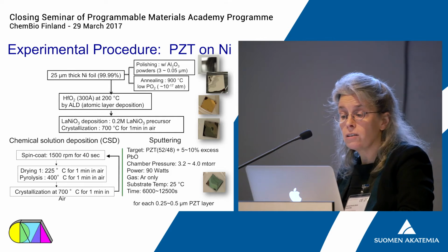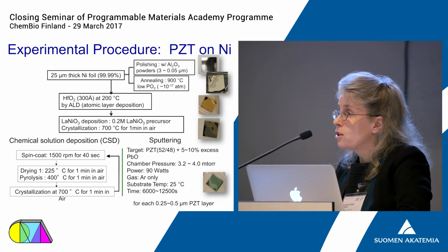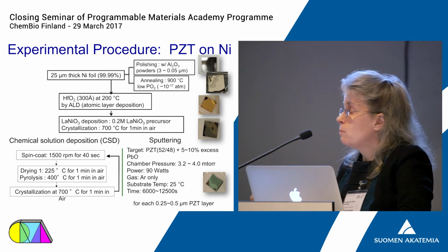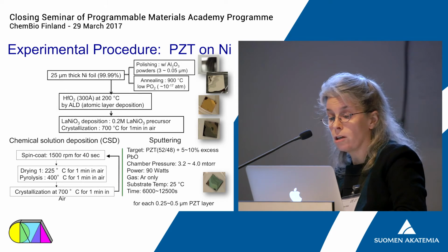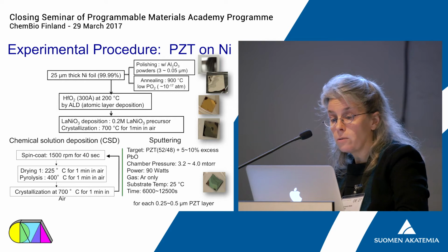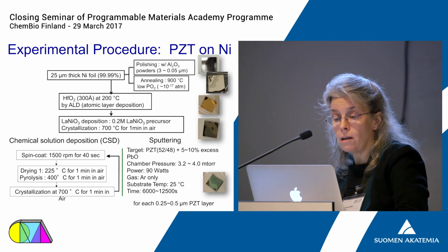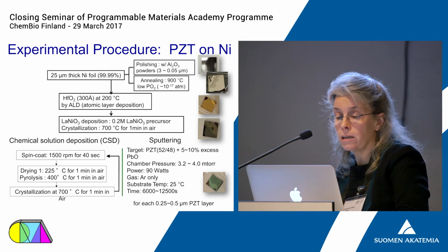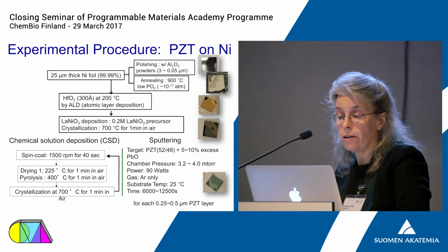They will deform plastically as needed, and they also have larger thermal expansion coefficients than lead zirconate titanate, so they offer the opportunity to be able to make machinable microelectromechanical systems as energy harvesters with good figure of merit, to be able to grow the lead zirconate titanate films on these devices. We passivate with a layer of atomic layer deposited hafnium oxide. We put down an orienting bottom electrode. This is an oxide electrode, lanthanum nickelate, and then we can grow either by chemical solution deposition or sputtering a very high strain, high figure of merit piezoelectric material on that device.